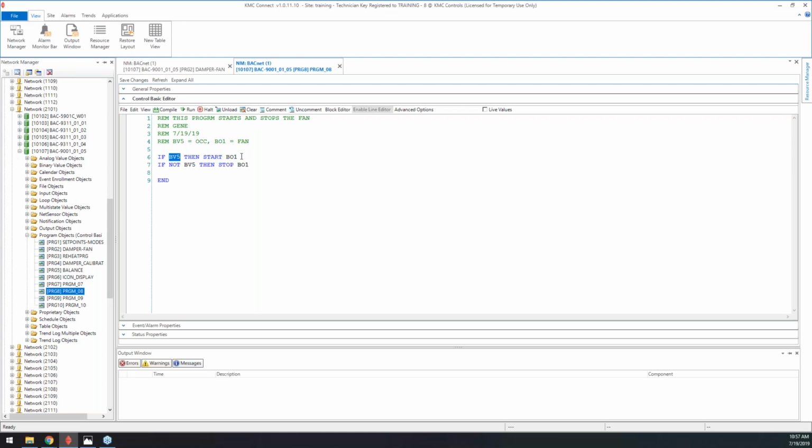Okay, so now we also have to remember, now that we've started BO1, somewhere we're going to have to stop it. So always remember that you have to stop whatever you start. So in the second line, line number 7, I have written: if not BV5, then stop BO1.